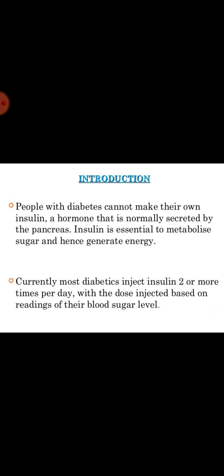Syringe pumps are usually of a reciprocating type. A plunger or piston delivers a fixed volume of fluid on each stroke. So they require valves and normally furnish a pulsating flow, which can be evened out by the use of reservoirs and by duplex arrangements in which the discharge portion of the stroking cycle is spread over more than the conventional 180 degrees. Piston pumps can be used at high pressures, and control is achieved by varying the stroke length or the stroke rate.